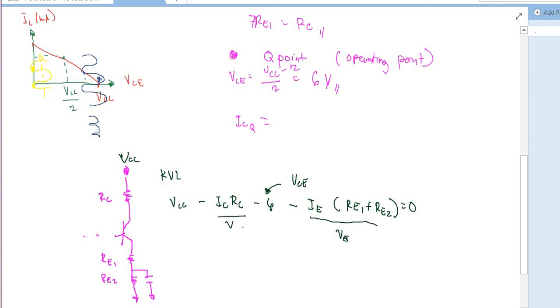So this is the VC. Okay, so by using common sense, you will notice that this one should have a voltage drop of 3 volts, and this one should have a voltage drop of 3 volts, and then this one is 6 volts. So that's why it's expected that in this one we will set this as having a voltage drop of 3 volts, and then this one also a voltage drop of 3 volts for symmetry purposes, so that it would be much easier to solve.